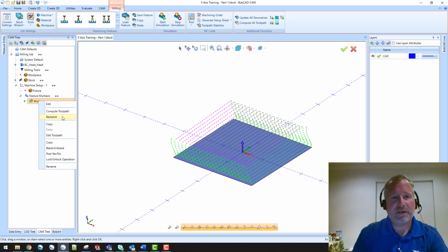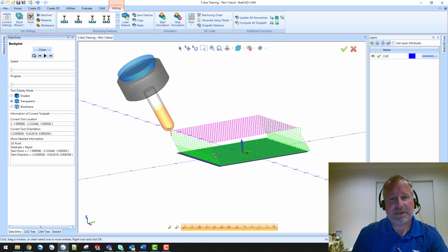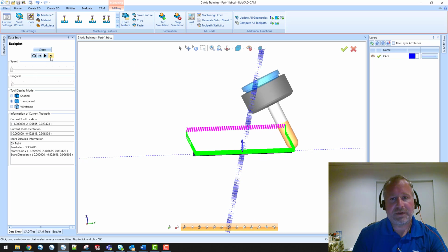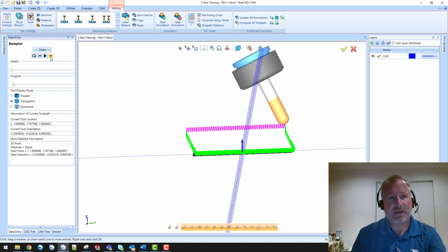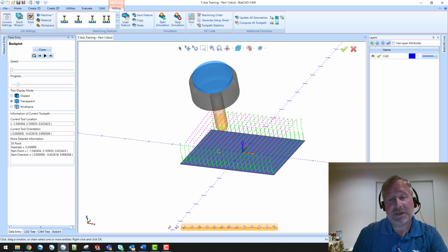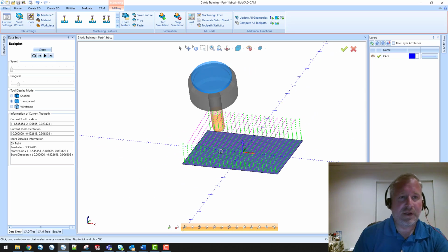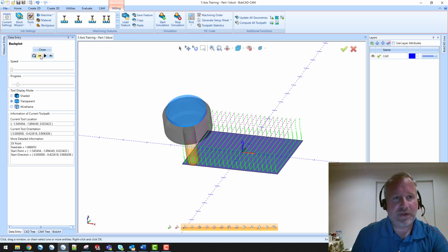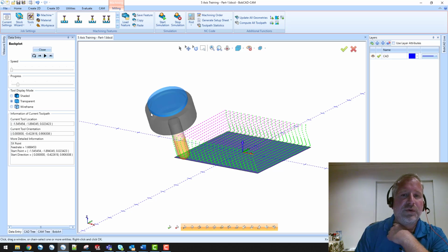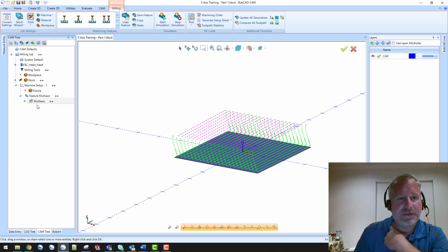So now the point of the tool is actually leading, and the tool is somewhat plunging, if you want to think about it that way, as it goes across that surface. Again, sometimes it's necessary to be able to kick that tool so that you can get into a specific area on a part without the shank of the tool or the tool holder colliding into something else.